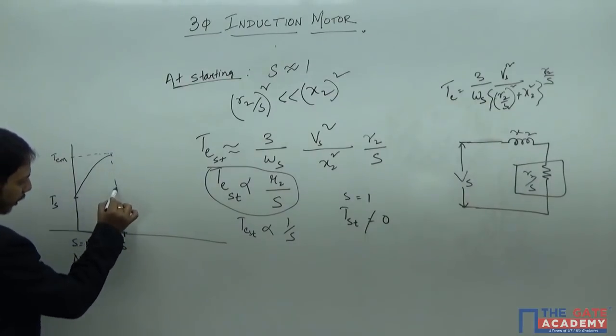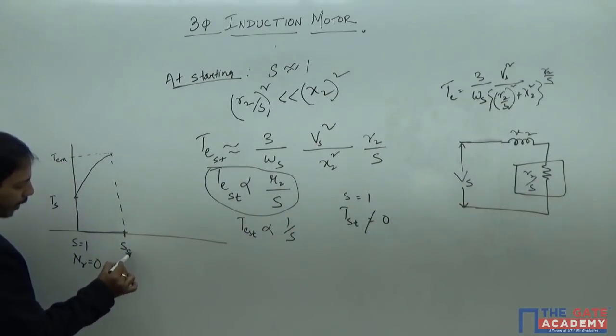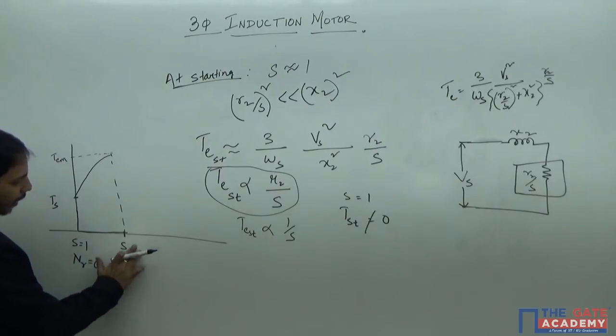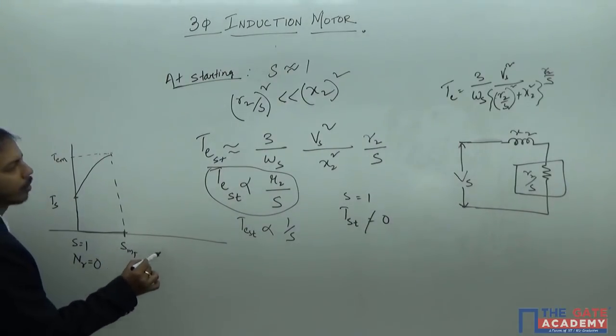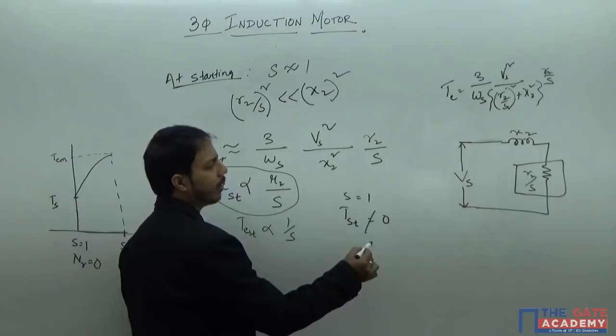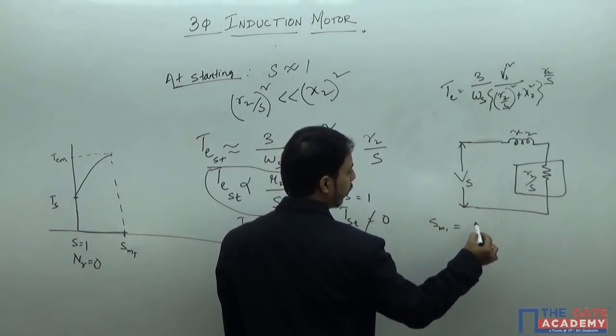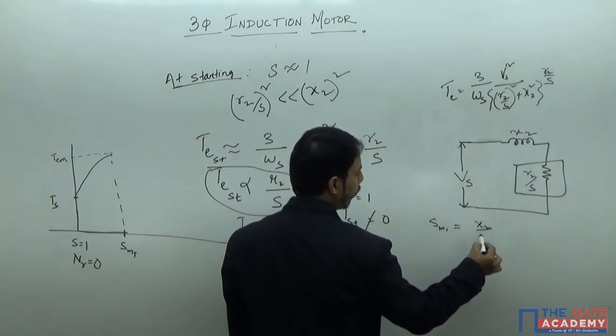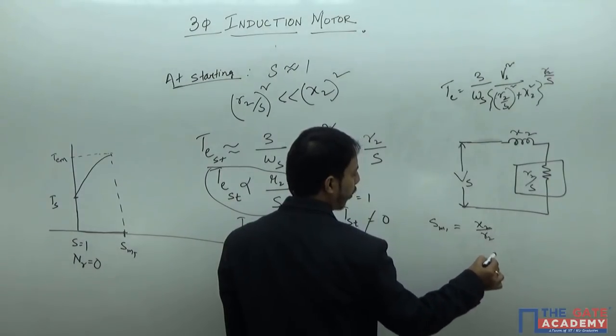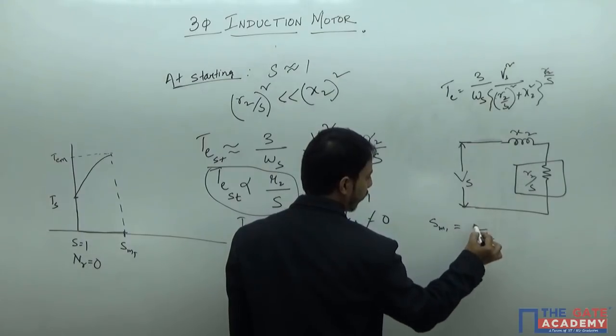This will happen at S maximum torque, SMT. And what is this SMT? This SMT is nothing but R2 by X2.